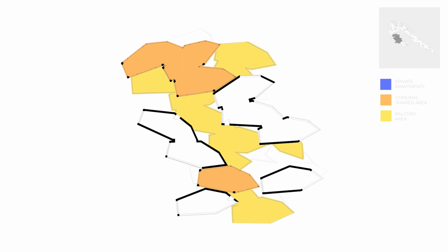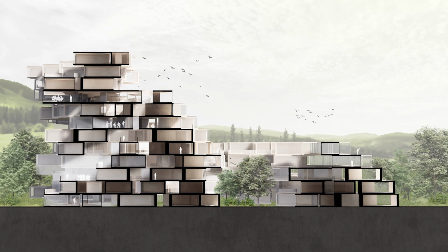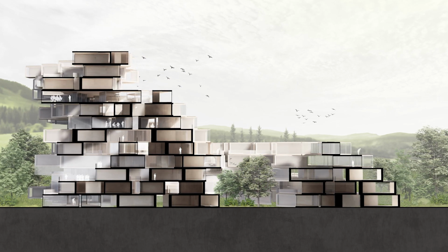Also, 2 types of shared space were created. One is full glazed with glass, another one is semi-open, allowing cross-ventilation and building up a connection with surrounding nature. The housing and shared area blended together to create this co-living co-working enrichment connected to nature. The system creates a void opening inside the building form which allows natural light to get inside and cross-ventilation.